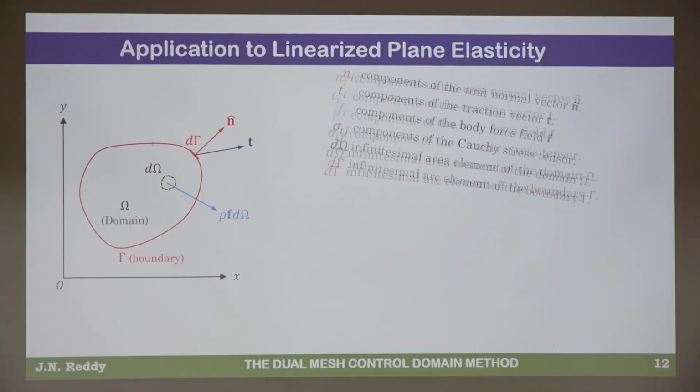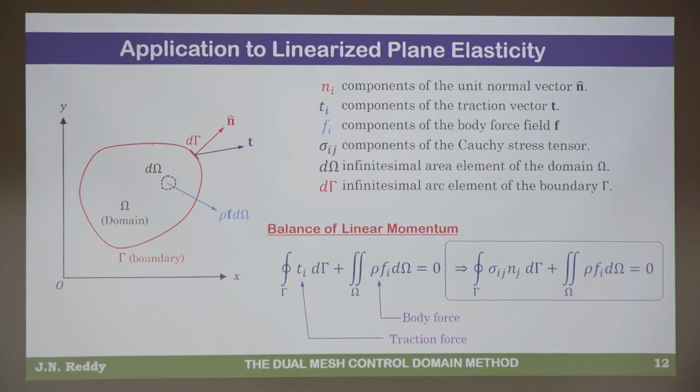Okay, so here again, I don't want you to read too much. So this is the global balance law of elasticity. See, this is the nice thing about the finite volume method, because it uses the physical law directly. No weighted integral statement. But the only thing is they don't have the concept of interpolation or duality. So this T_i is a dual variable. It is the traction. See, I should not think of replacing it with some derivatives, okay?